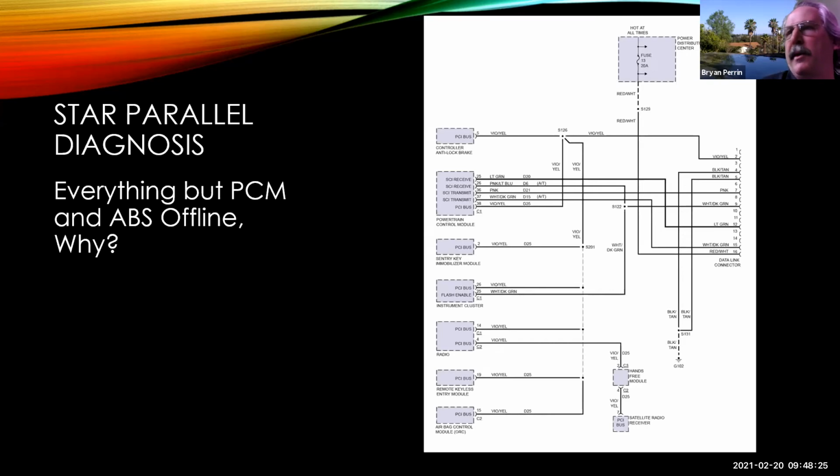So I'm probably going to step this in a couple of things. I got my initial hour. Now I'm going to get however much time I need to get to 201 and do my tests. Plus, once I get to 201, could I use a jumper wire from splice 106 to splice 201 to see if I can talk to everybody?